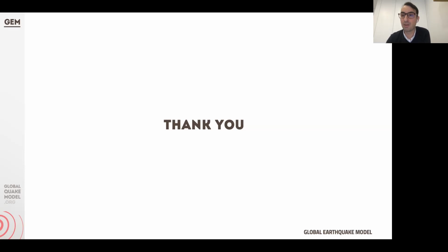And then you can use all the information that is coming out of this ground motion records to predict the structural response. We actually did a lot of tests comparing how vulnerability and fragility functions behave against artificial neural networks by using directly the results from dynamic analysis, and everything is better using that in terms of sufficiency, in terms of efficiency, and also in terms of accuracy.